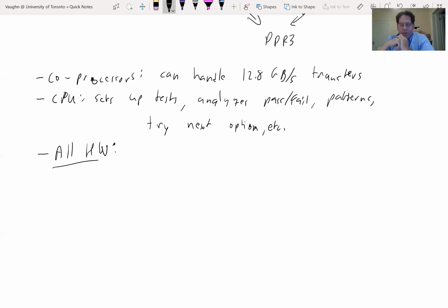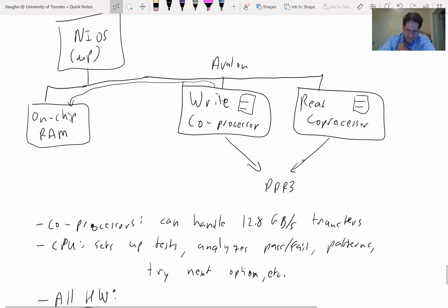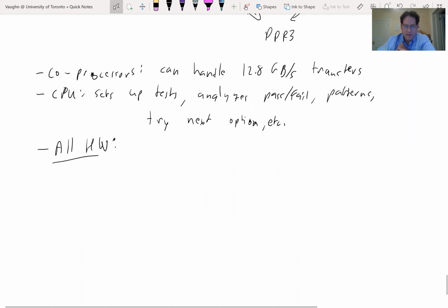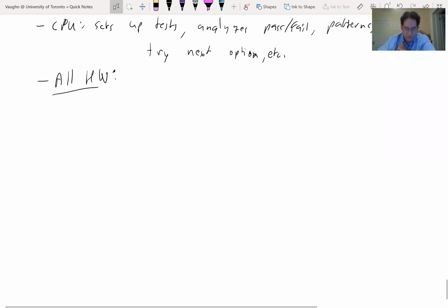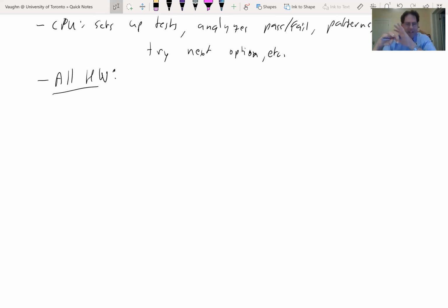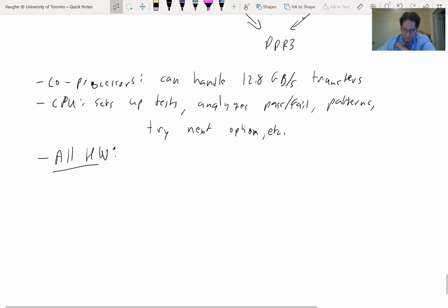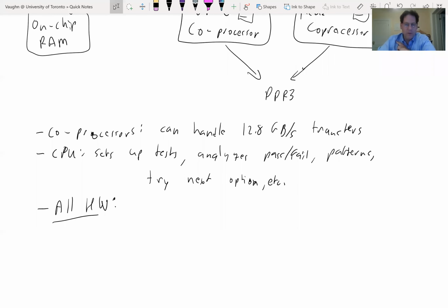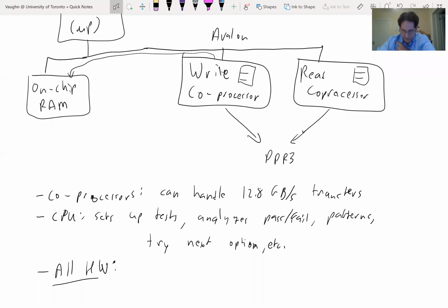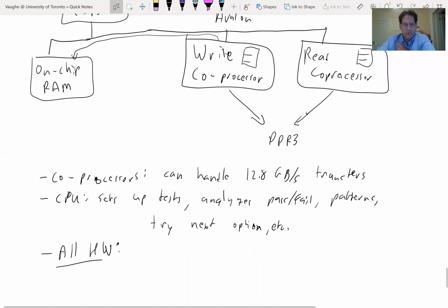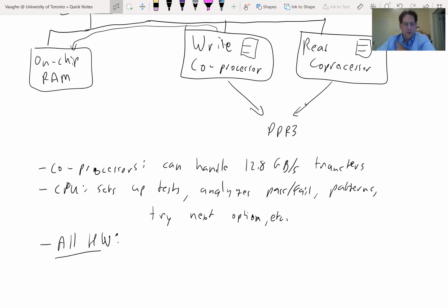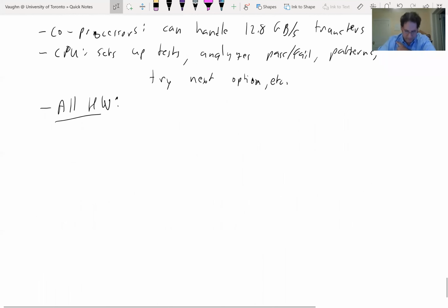And that's actually what the previous generation of IP cores for this did. They didn't have this structure of using a microprocessor to control coprocessors. They basically did it all in Verilog, built big finite state machines that were directly controlling certain hardware units. And they hadn't scaled to the highest frequencies. So they actually couldn't reliably calibrate to DDR3 at this frequency. So the calibration algorithm was going to have to get more complicated. So this all hardware solution needed some updates as well.